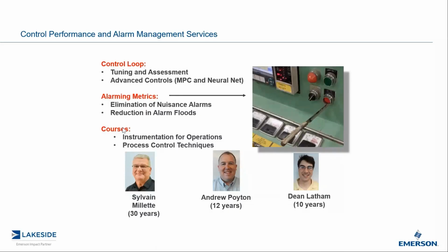DCS alarm metrics. Anybody look at your DCS alarm banner? A lot of times, if you walk into a control room, typically it's full of alarms. A lot of them are maybe unacknowledged. Some of them are irrelevant. So the services we offer is that we do an alarm analysis. We could do a download of your alarms for a period, let's say 30 days, go through and establish which ones are nuisance alarms, and we work our way from there. The idea is not to eliminate alarms. The objective is to make the alarms relevant to the operator.